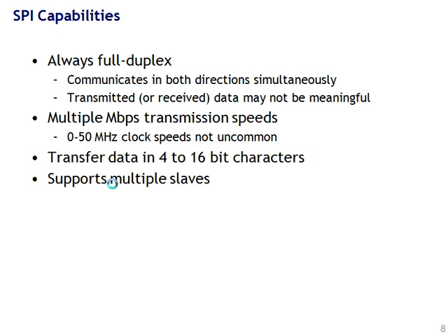Let's see now. 50 megahertz clocks are not uncommon. That's perfect for microcontrollers. 8-bit toaster controllers that run at a megahertz or 16 megahertz are common. And in its quiescent state, the tiny version of the Arduino runs at nanowatts.